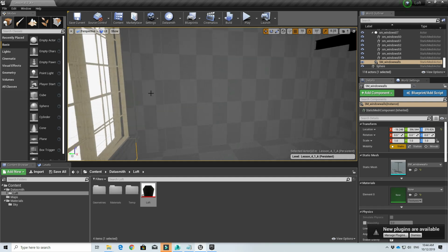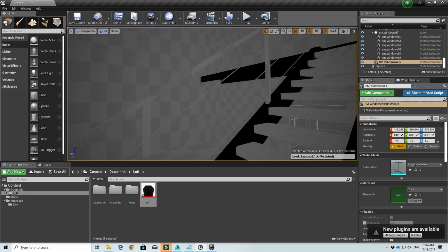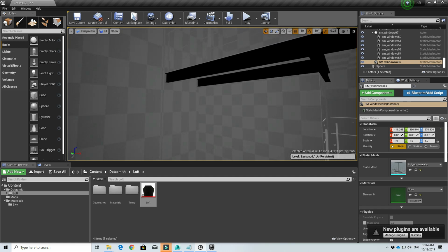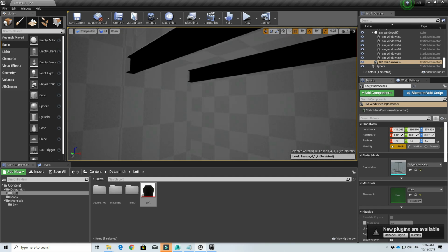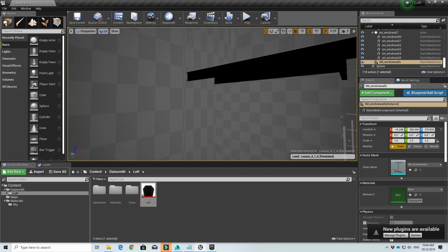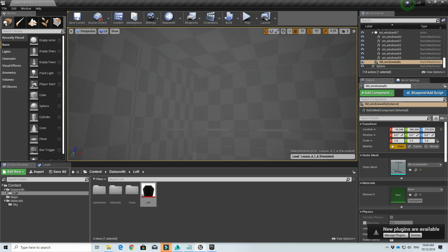It doesn't have to be exactly the same, but as long as they are about the same, we can have an easier time adjusting the UVW mapping later, especially since the materials we're using are bricks, so it's really okay not to have the exact same size. We just don't want squished up UVW mappings.